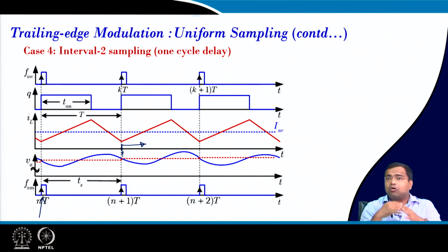And then what could be the alternative arrangement even with this delay, because you may not need a very fast ADC. One possibility, you may increase the sampling rate when there is a transient, or you may create an additional path to bypass and avoid such large delay during a large transient. So, there are many possibilities.